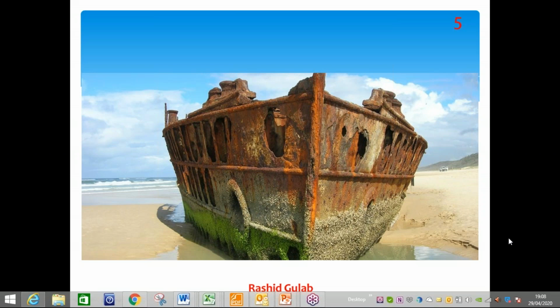In the natural phenomena, only copper and the precious metals gold, silver, platinum are found in nature in their actual metallic state. All other metals, including iron, are processed from minerals or ores into metals which are inherently unstable in their environment. All man-made metals are unstable and have a tendency to revert to their more stable mineral forms. Some metals form protective ceramic films, you can say passive films, on their surface, and these prevent or slow down the corrosion process.